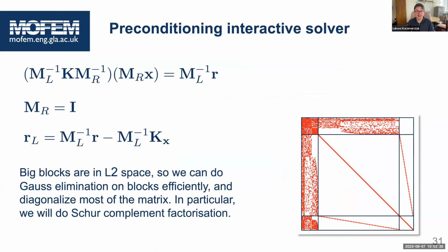If you want to solve large systems, you want to solve them using iterative Krylov solvers, but iterative Krylov solvers work well when you apply preconditioners, and you can have two types of preconditioners, left and right. Here we will assume that we are only using a left preconditioner. What the preconditioner tries to do is make our matrix K as diagonal as it can be.